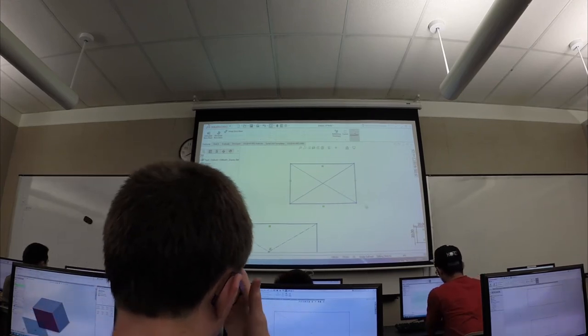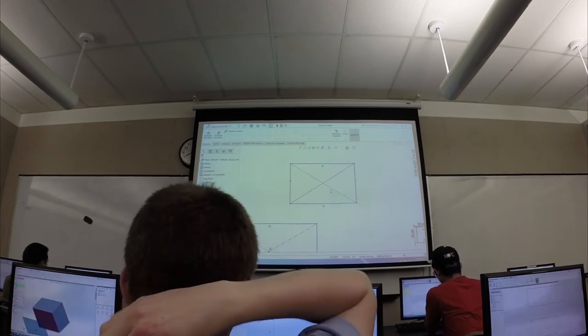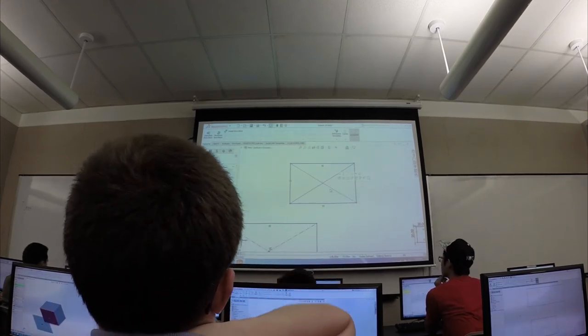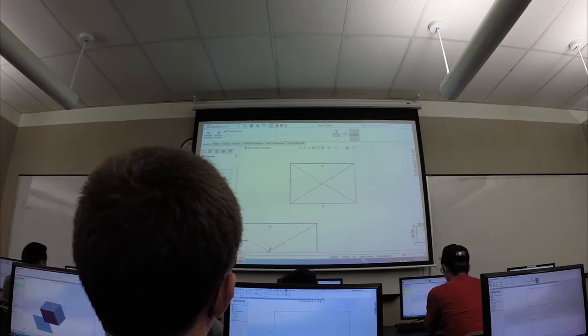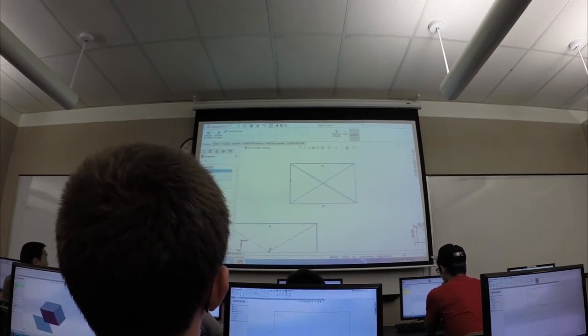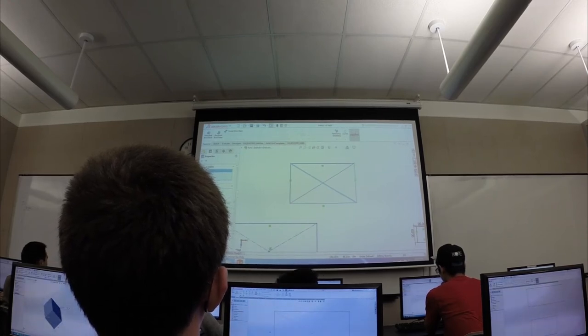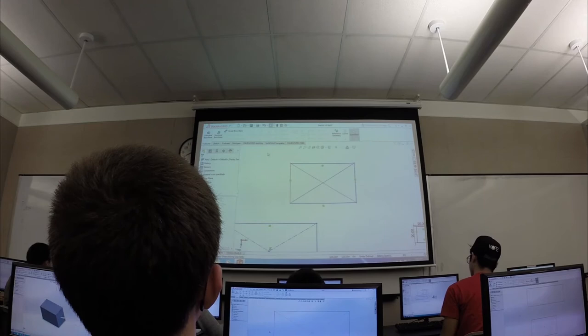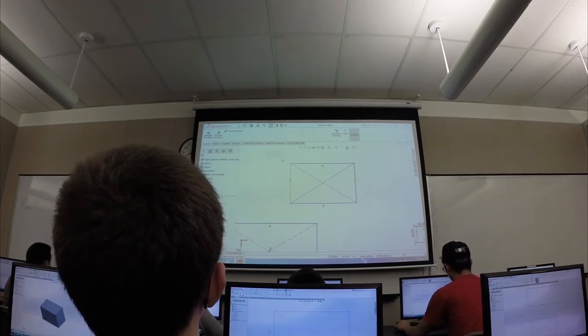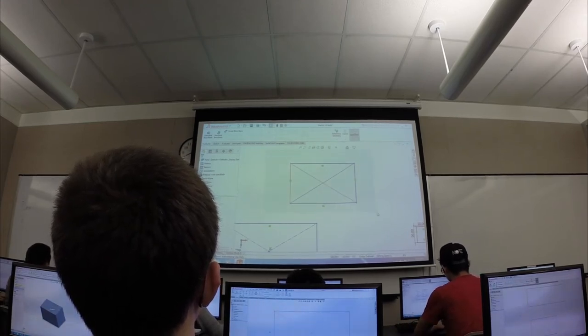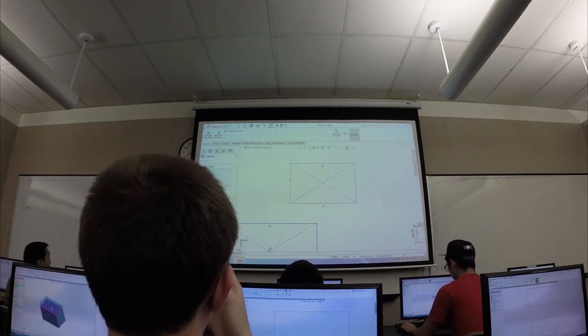So if I were to drag this way over this geometry and then select this green box, I let go. You'll notice that these lines are selected, right? So when you have that green box, anything that's within that box immediately becomes selected, even if it's partially in that box. On the other hand, if you drag in the opposite direction, so you have the blue selection box, as soon as I let go, it doesn't select anything, right? You're like, what's the point of that? However, if I stretch this blue box all the way around this part, it selects all these lines.